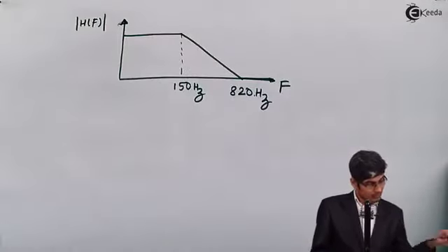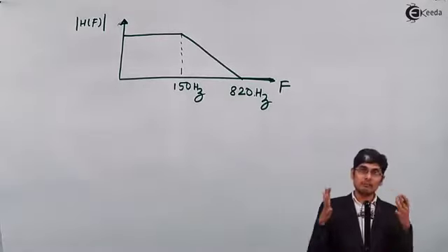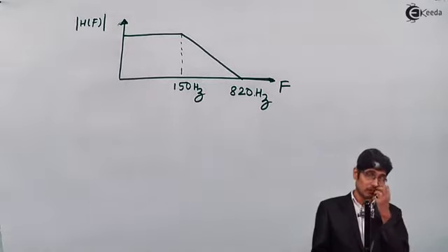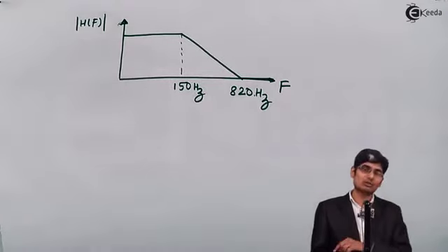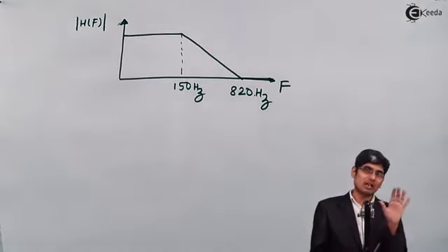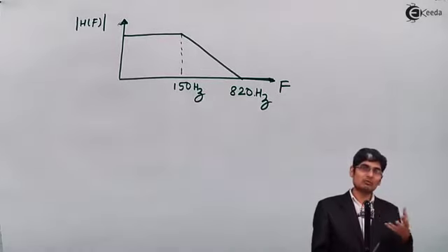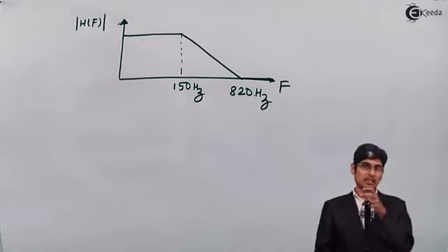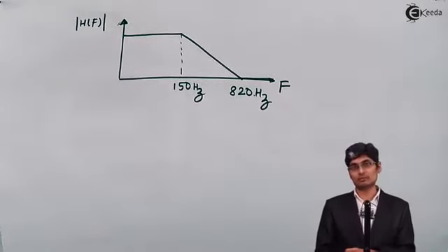So if I want the overall passband ripple of a cascade structure to be 0.02, and I make a 0.02 passband ripple in stage 1 and stage 2 also, then at each stage I am going to add more and more ripples. So the passband becomes more rippled because the total ripple that I have added in the cascade structure is 0.04.